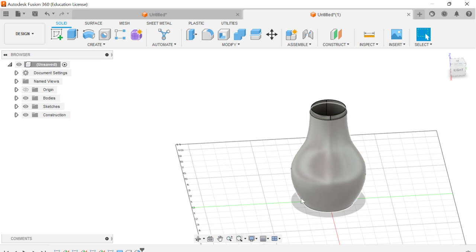So you have to click on one of the planes or the X, Y, Z at the bottom. But for your body, go to the body icon in the browser. And now you won't interfere with the body, and you can have an offset plane. That's perfect. That's perpendicular to the outside of the body on your side.